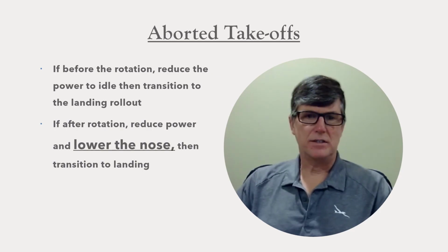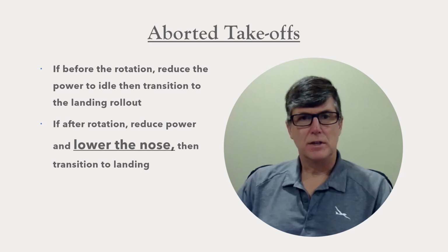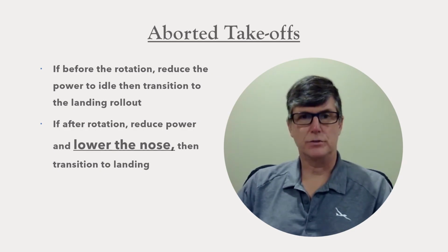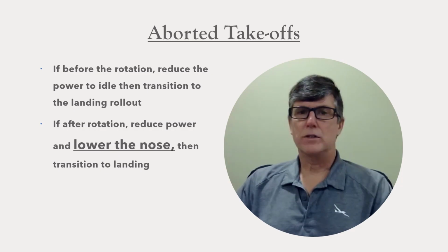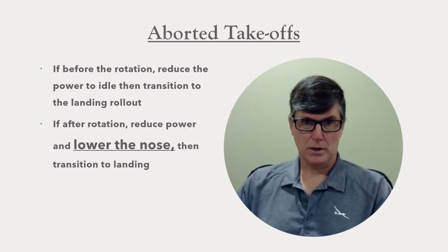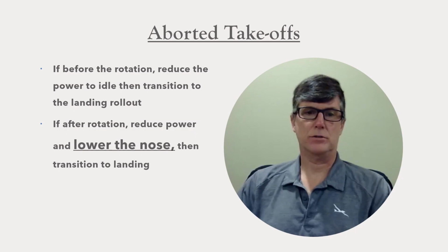After rotation, it gets a little more complicated. You'll reduce the power, then you need to lower the nose, and then you need to transition to whatever phase of landing would be appropriate for your altitude. Lowering the nose to maintain your airspeed is crucial at this point. Airplanes slow down very rapidly if you reduce the power and the airplane is in the climb attitude.